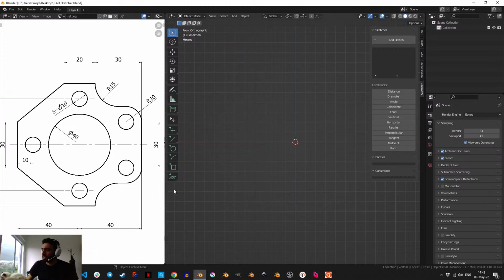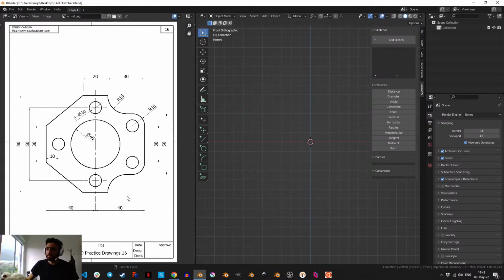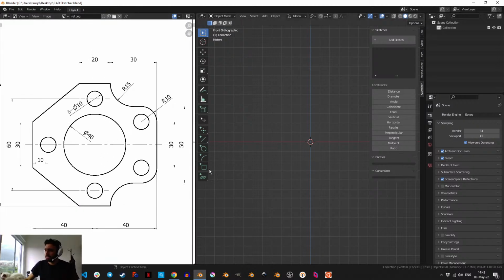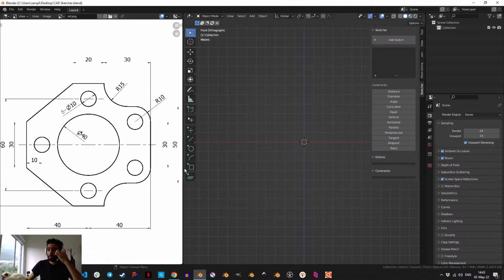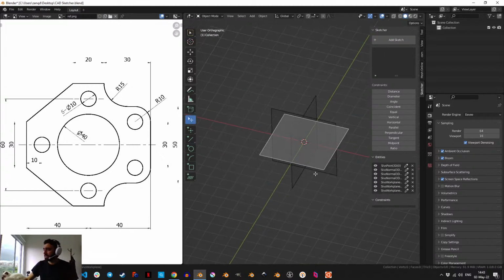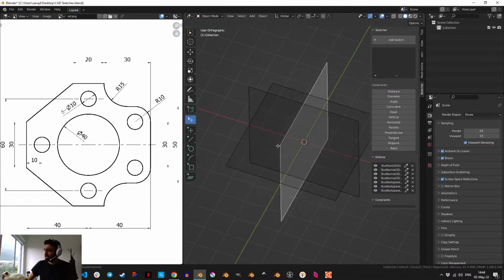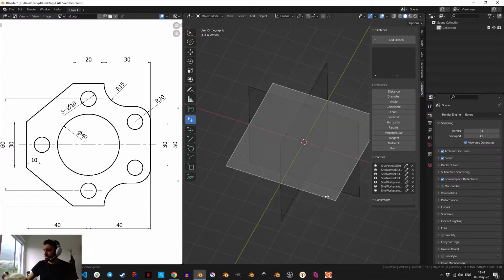All right, so I've been having a lot of fun with CAD Sketcher, and I think I know a little bit more on how to use it. So I'm going to be trying again with this shape I got here. At first, what I want to do is create a sketch, and this way you can select a plane to work with. And I like to work on the floor plane, which is defined by X and Y axis.